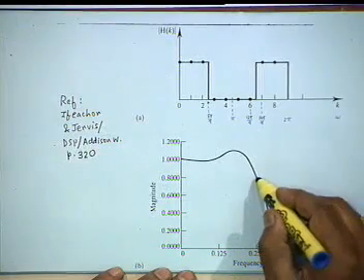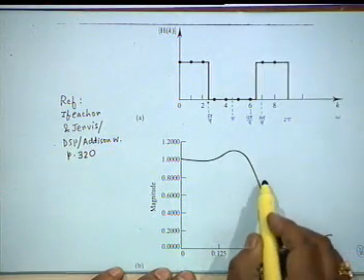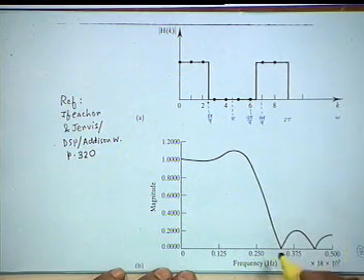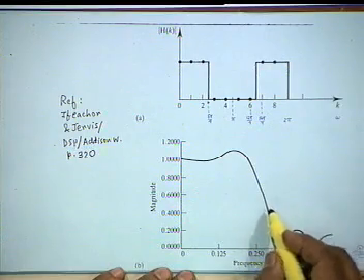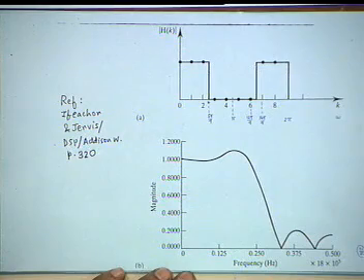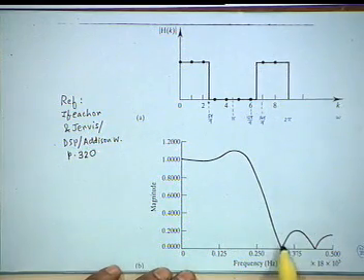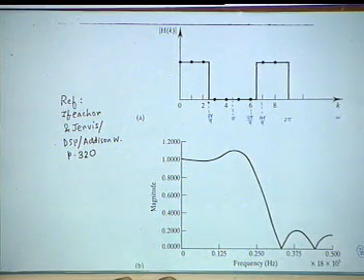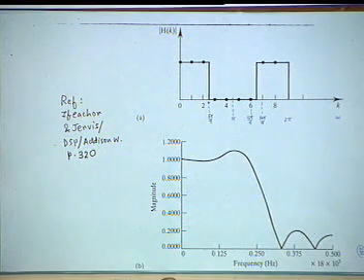Somewhere here is the cutoff frequency, but you see what, pardon me, 0.28, so it's somewhere here, and you see the wide divergence, wide tolerance that you get, okay, and there is a tolerance, this is also pretty wide, 0.2 in the stop band. It's a very bad design, okay.